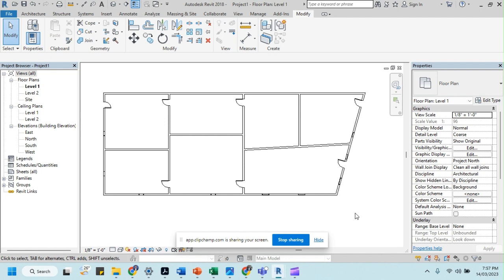And another option there is called crossing selection. Objects that cross this box will be selected. You can see that the wall crosses the selection, and all of this wall is added to the selection. You can see there is no need to come into the entire window, it only needs to cross. With that you can see a dotted line. If the dotted line crosses any object, it will be added to the selection. We call this method crossing selection. There are two methods. Drawing from top to bottom we call window selection. When we draw the box from bottom to top, it is called crossing selection.